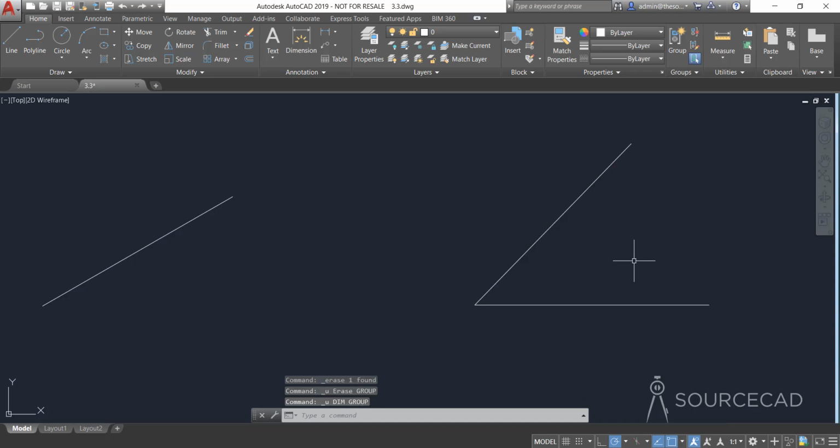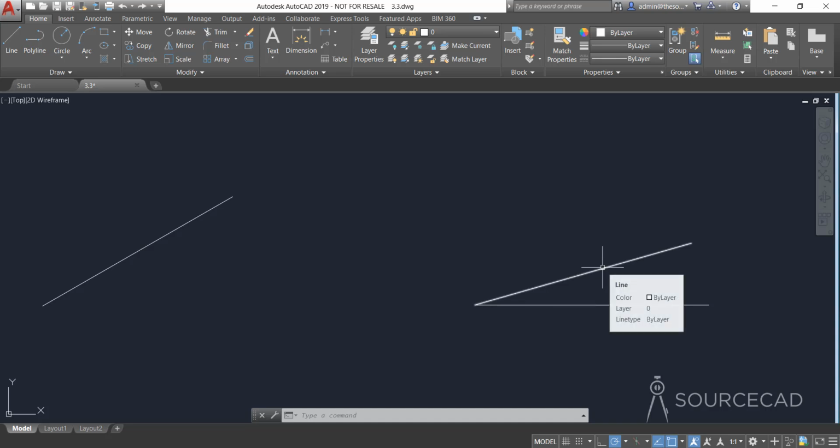So that's the whole thing about the rotate command. Rotate command will always rotate your drawing with respect to its original position. In this case, this was at 16, so it made a final angle of 30 degrees with respect to this line. So if you measure it with respect to this, then you'll get 30 degrees. I'm going to do that next.